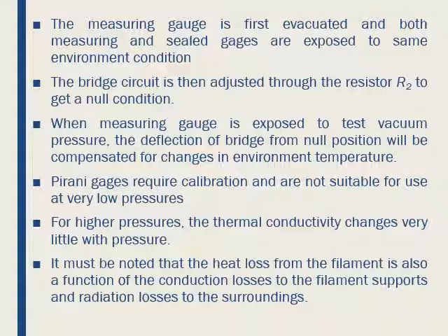Pirani gauges require calibration and are not suitable for use at very low temperatures. For higher pressures, generally, the thermal conductivity changes very little with the pressure. Further, it must also be noted that heat loss from the filament is also a function of the conduction losses to the filament support and the radiation losses to the surroundings.